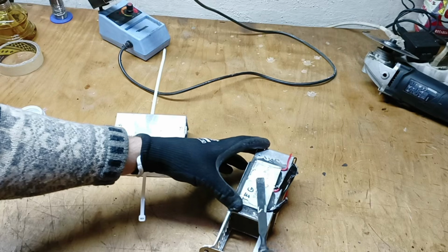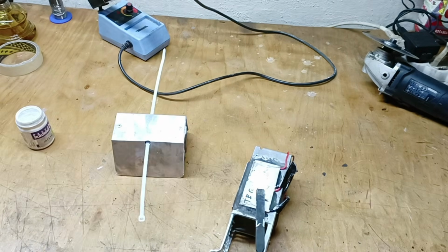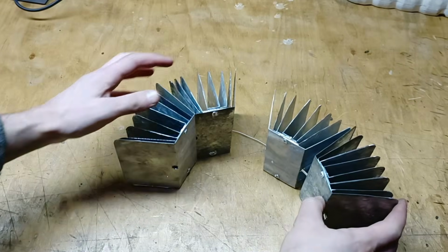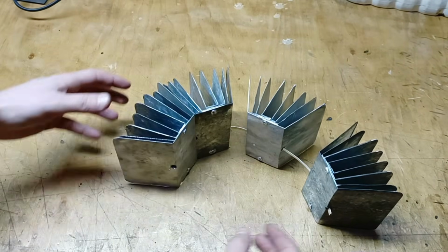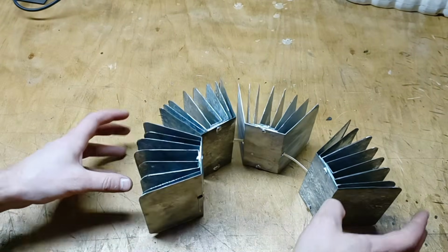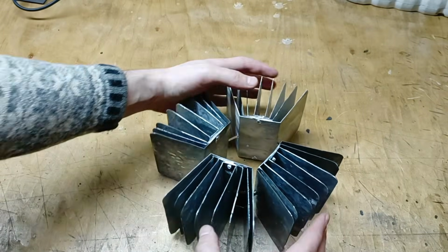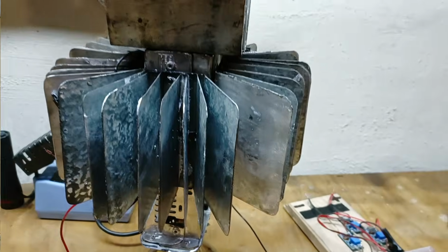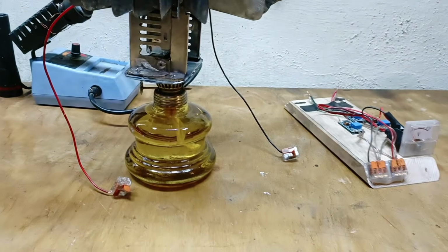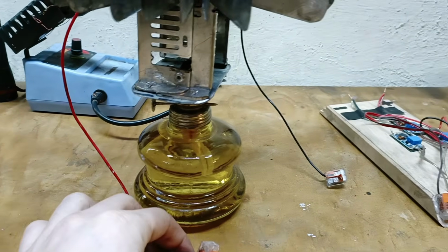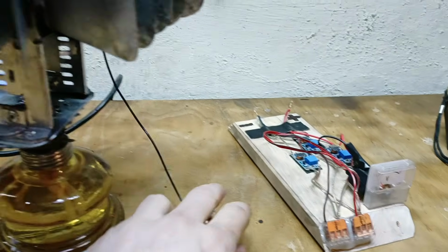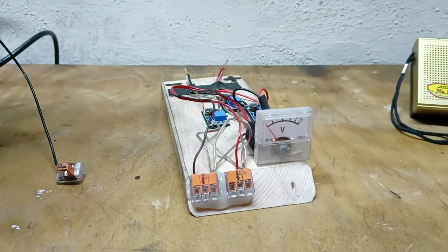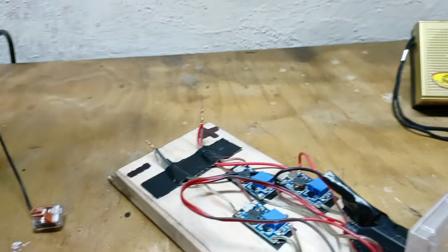supportive structure, of course remembering to first apply thermal paste to each cell. As I mentioned in a video when I was building the heatsinks, they will be pressed onto individual cells using a steel cable tie. That's why I drilled 2 additional holes in each steel plate. And this is what it looks like after putting everything together. I think it turned out pretty cool, maybe a little steampunk-esque, at least in my opinion. Of course, the red wire is positive and the black wire is negative voltage.